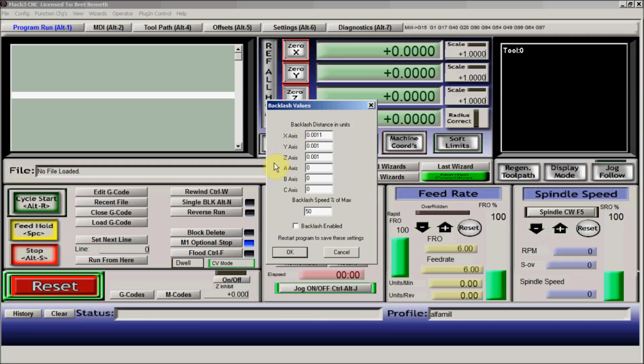It'll come around one side and stop momentarily and do a backlash compensation. It'll stop at all four corners every time it meets a place where it would change direction. Say, if it moved full distance in your y-axis, then it would want to do a backlash compensation.